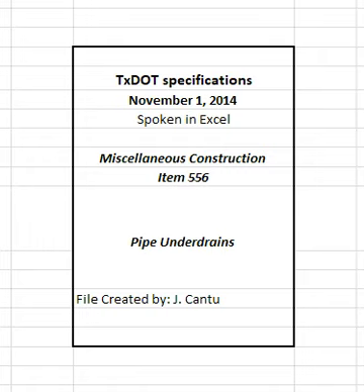Lap filter fabric over the top of the filter material after placing pipe and filter material according to the manufacturer's recommendation or as shown on the plans. Figure 1. Installation process. See figure in specifications. Install non-perforated pipe sections between the perforated pipe and the outfall. The sections of non-perforated pipe do not require filter fabric or filter material.